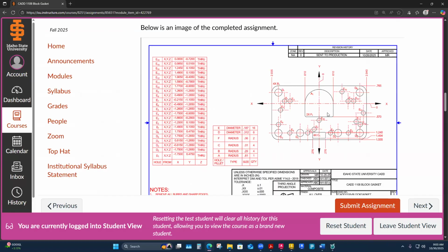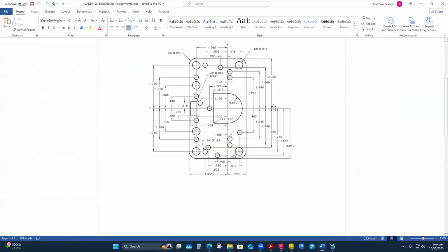But I could see that some drafter would read those same instructions and say, well, I rotated mine the other way. Does it matter? It probably would matter, especially if I'm building something by coordinate points. But it's not clear on the assignment sheet which way I've rotated that, unless you have my little example here. So I should designate which one is the Y. The assignment sheet would be better if it said this is the positive coordinate value quadrant here. I should add a note that says make this corner in the positive quadrant, which is what I've done.